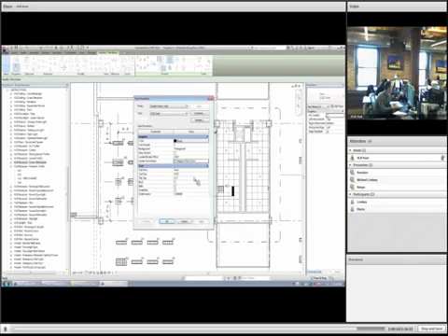Let's talk about some of the other controls that are here. First of all, the color. The line weight is fairly standard. Don't mess with this. There are 16 line weights in Revit, 1 being the lightest, 16 being the heaviest. Generally just leave this at 1. The background is either transparent or opaque. I find an opaque background semi-annoying with text, because if you have floor patterns or ceiling patterns, you'll see a big white box around the text. I normally leave it transparent.